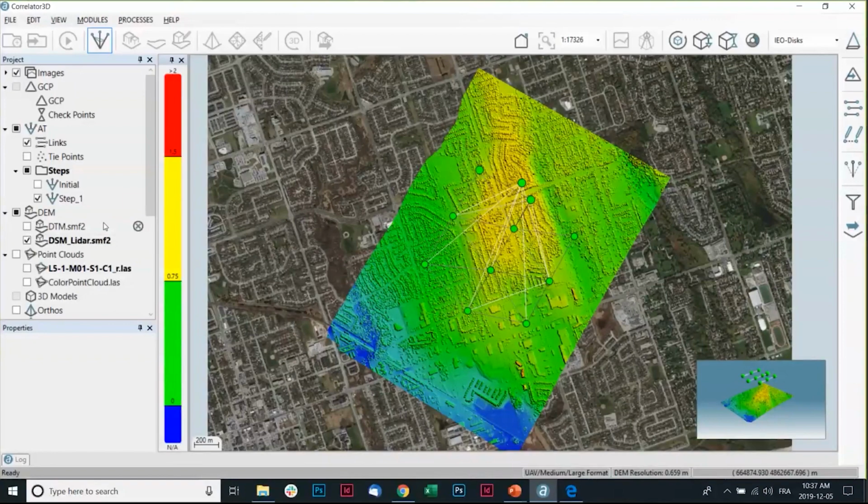Also, if you want, you could bring your LiDAR DTM. Let's say you are in a forest environment, and you want to have your forest mapped on a DTM without the wobbly effect over the trees that you get if you're using a surface model. Well, you could bring your terrain model and do the ortho rectification straight on your terrain model.